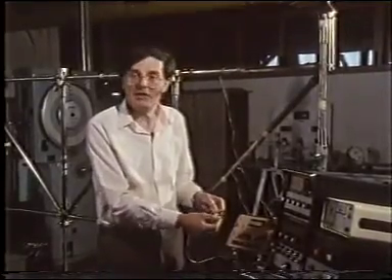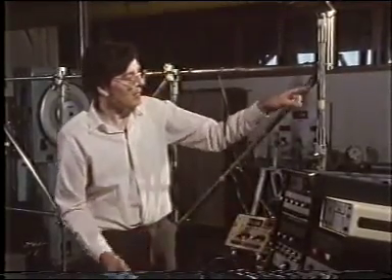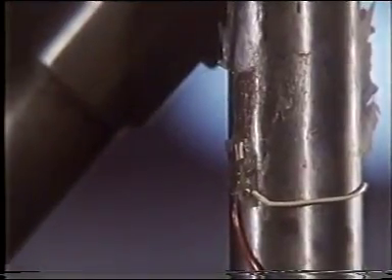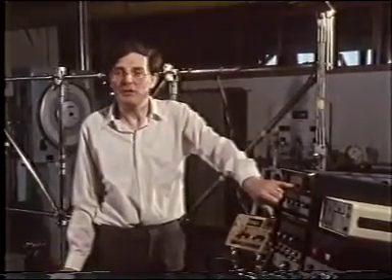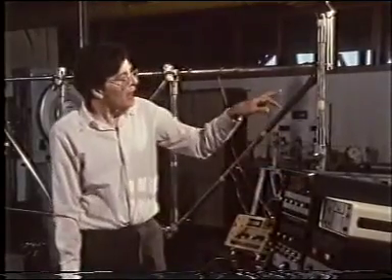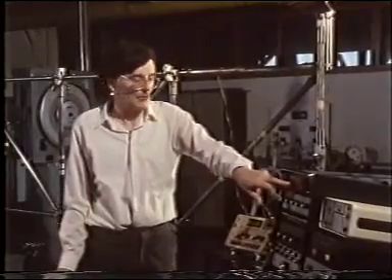So by measuring the extension in this way, I can get a direct reading of the load. I've previously calibrated this member, which has a strain gauge on it, and this gives a reading of 1 digit on here for every 1 newton of load. So that I can now read the forces in these two members directly on this meter.